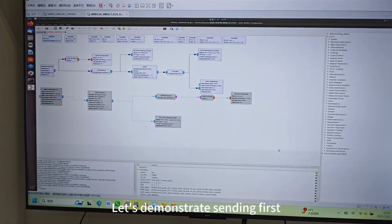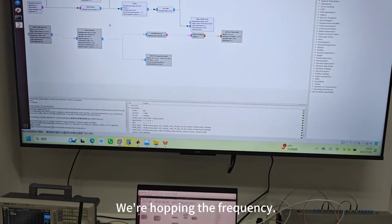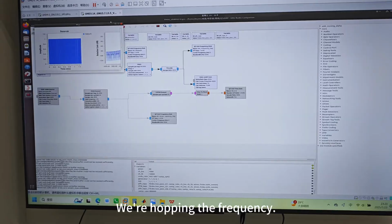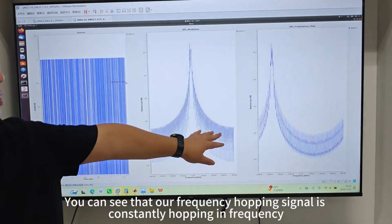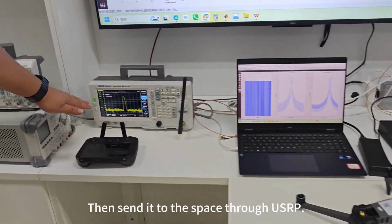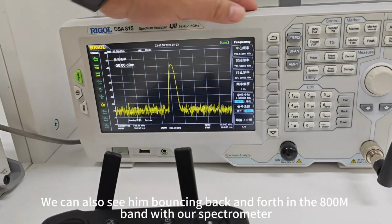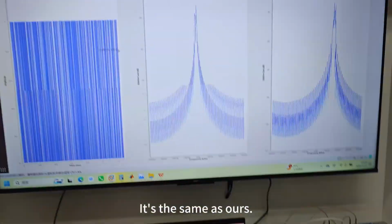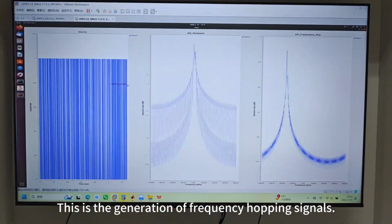Let's demonstrate sending first. We're hopping the frequency. You can see that our frequency hopping signal is constantly hopping in frequency, then sent to space through the USRP. We can also see it hopping back and forth in the 800 MHz band with our spectrum analyzer. The central carrier frequency is 800 MHz. This is the generation of frequency hopping signals.